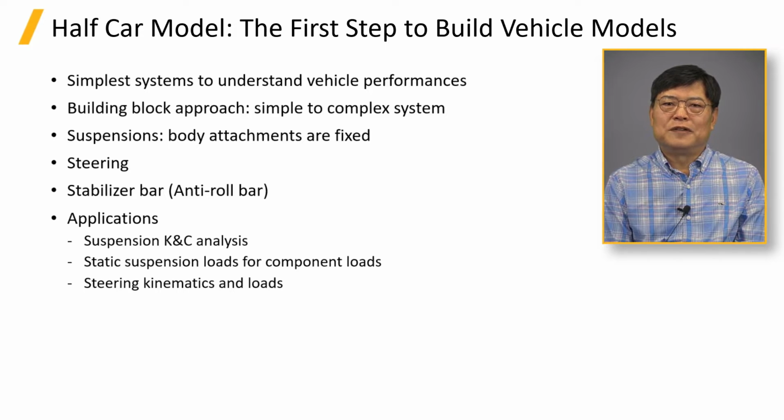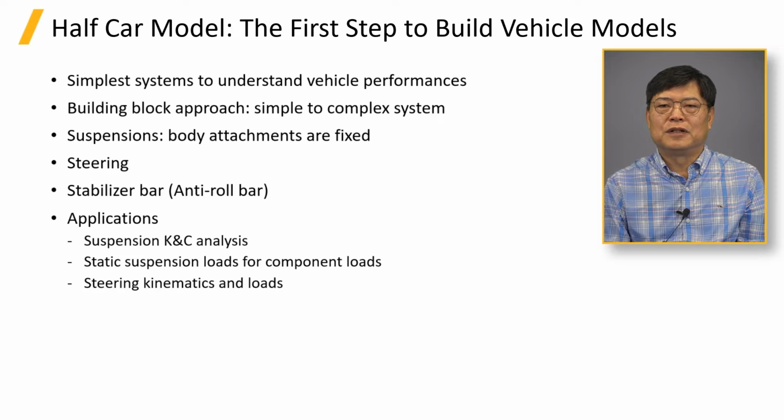One of my favorite steps is to apply a huge force at wheel center and tire patches. You can easily figure out load paths graphically. Excessive deformation at suspension attachment due to improper bushing representation can be easily detected. Don't forget to turn force and moment graphics on.